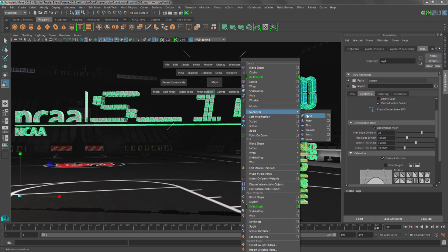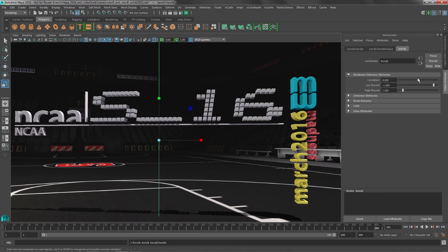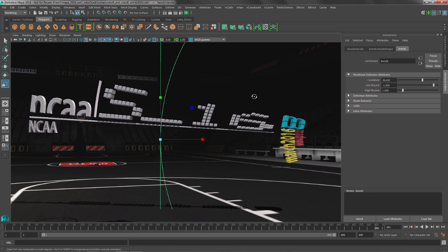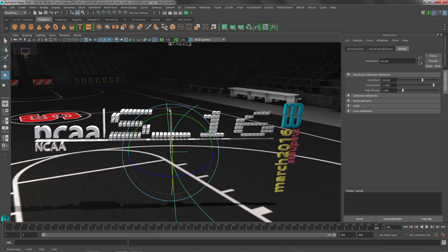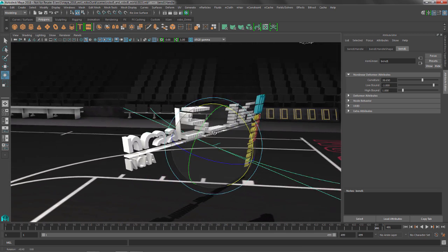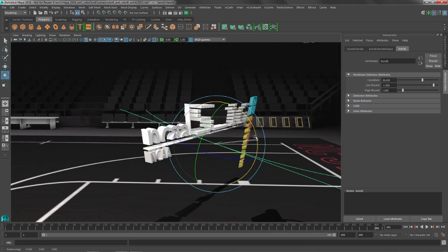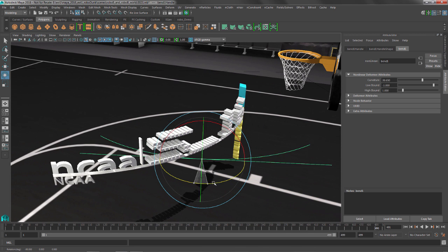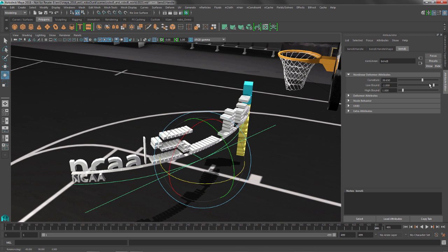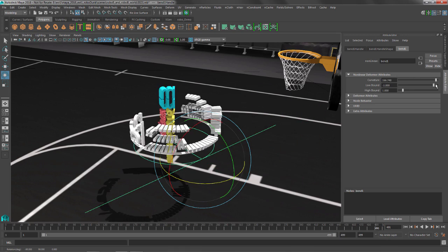So we'll go ahead and grab this nonlinear bend deformer. We'll give a little bit of curvature on that guy. Now obviously objects can pass through these nonlinears, and these nonlinears can be positioned and rotated. So what we're going to do is hold down our J key to spin that guy around, something like that. Oops, I got to get one more snap on that guy, and then we're going to spin it around so that it's going down the length of that line, and now I can use this nonlinear deformer to do some fun stuff with this.